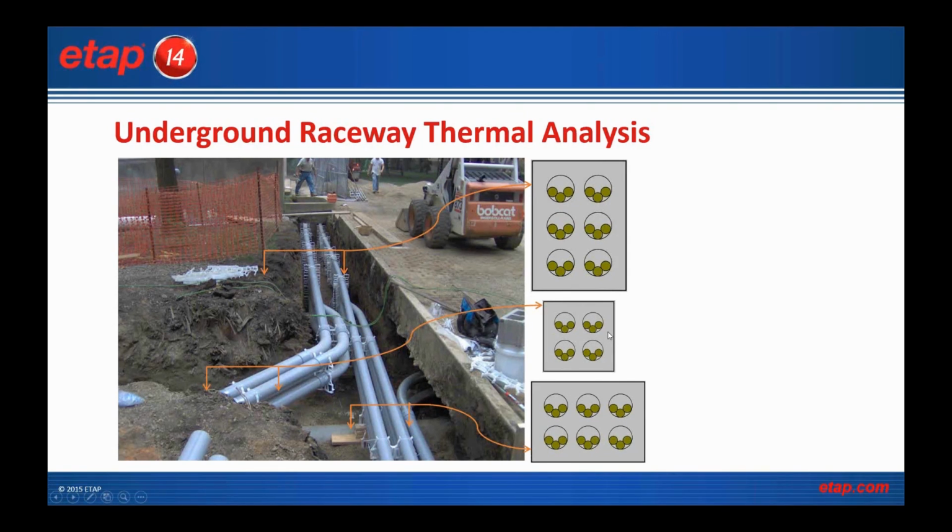An example of the elevation is where the raceway is being passed under a bridge, an overpass, or it's approaching a railway line and the duct bank needs to be pushed deeper into the ground to go under the obstruction and maintain minimum clearance. In that case, you may have exactly the same configuration cross section, however placed at a different depth from the surface of the soil.